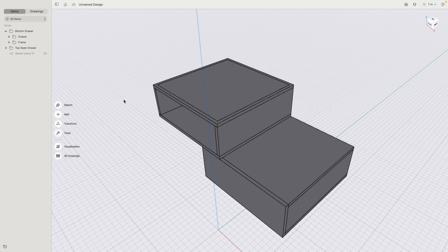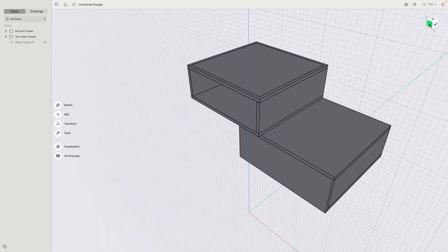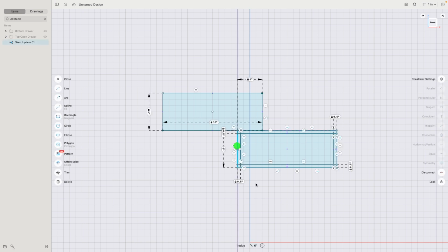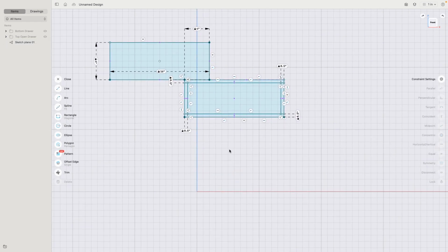And you see, that is actually how easy it is to create something in a more conceptual or with a more detailed sketch to work more precisely. At this point, it makes sense to think about the frame everything sits on. So let's go to the front view. We'll turn off the boxes, show the sketch. Here, I will select these 2 lines and lock them so they can't move.